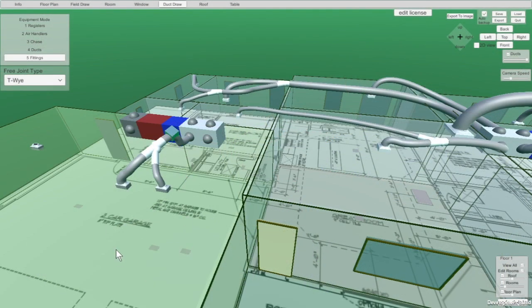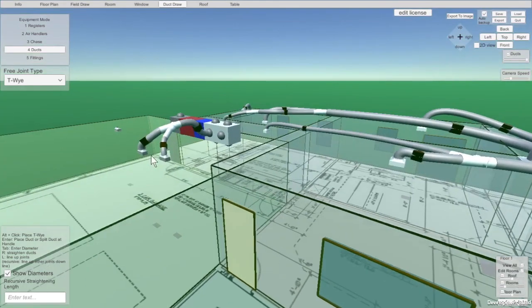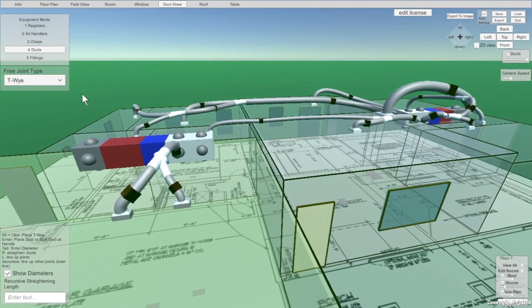Another cool feature is kind of a hidden button. We'll have to put documentation on this. But if you go into ducts, click on a duct and hit the R key, it straightens them out. It takes out any unnecessary bends. These were all pretty straight, but like so. On this joint here, you can change it; there are different choices: hard elbows, a true T, hard elbow 45s, splice, pants Y, things like that. It doesn't have to be a regular TY. You can put that in.